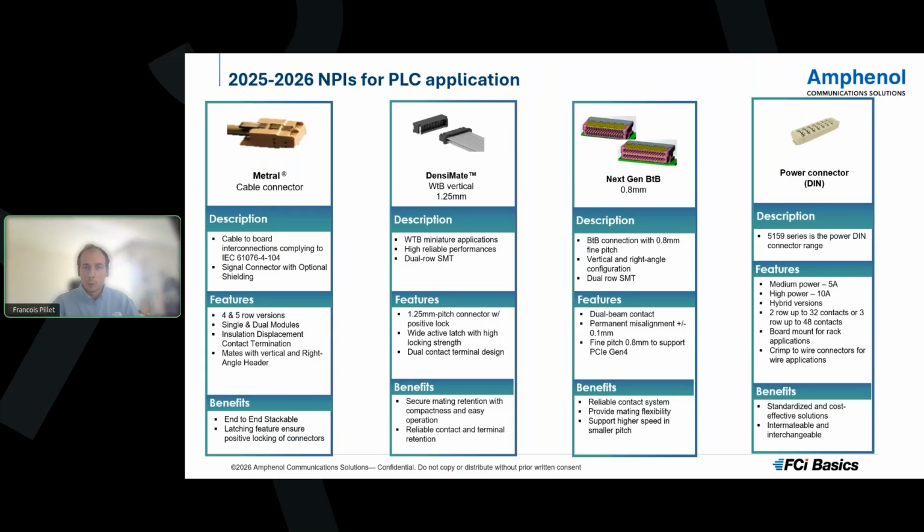Third, our next generation of board-to-board connectors will feature also dual pin contact and upgraded design to prevent misalignment of plus or minus 0.1 mm, and will also support PCIe Gen 4. The 0.8 pitch will remain, thus making this solution a very compact connection.